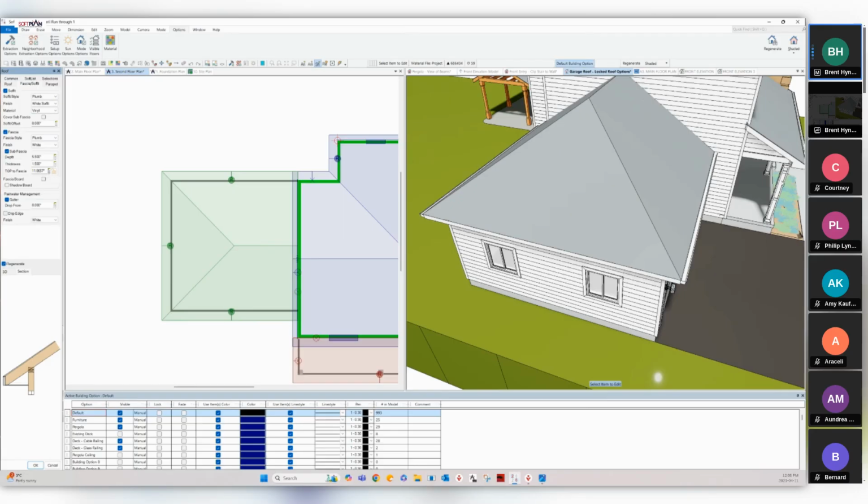Okay, now if I was to do that on an individual edge, obviously that's going to misalign the corners with some of the other edges on the roof. This comes into play mostly when you're trying to turn a corner where you have different pitches on the roof and you want to align the fascias. So at that point, you might go back in and you might lock the top to fascia number, okay, so that it stays put at that point. And when that's locked in, if you go back to the roof tab and you were to modify your heel height or change your pitch, that number will stay put, meaning that the fascia line will continue around.